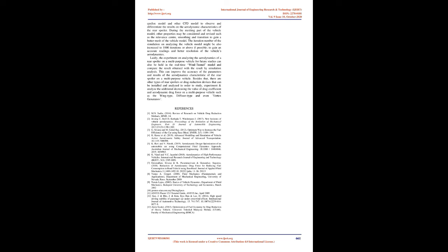Besides that, the result also shows that there is nothing much change on the lift force. This is due to the weight of the car itself, with 1,422 kilograms, and since multi-purpose vehicles are normally heavy, the lift force cannot be reduced much even with a mounted rear spoiler, and thus the lift force on all the three models of the vehicle remains more or less the same. In conjunction with the analysis and results obtained, the objectives of this project are very well achieved, since the analysis results are well associated with the multi-purpose vehicle's rear spoiler's characteristic aligned with the theoretical and conceptual approach of vehicle aerodynamics.